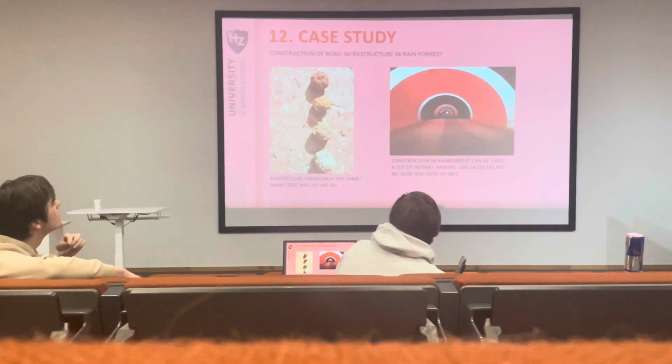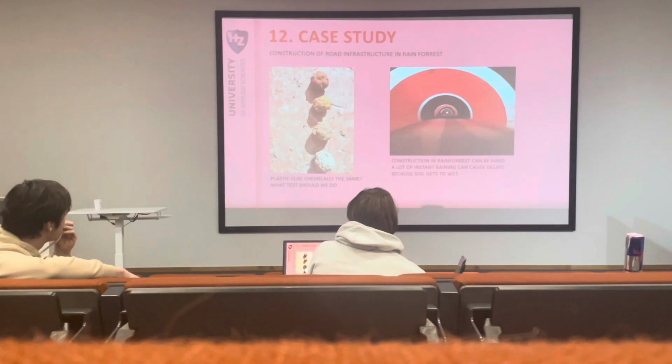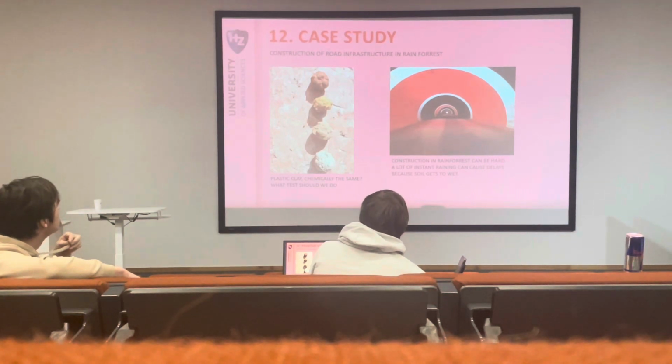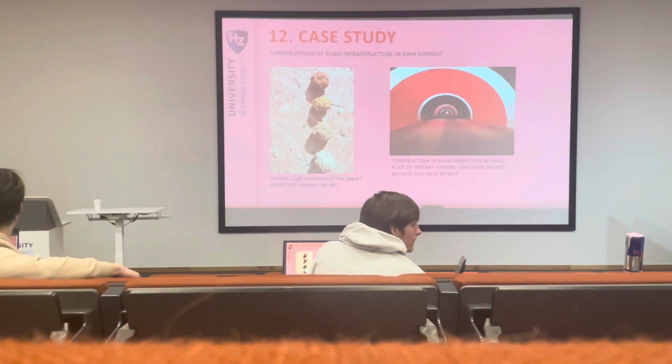There you can see also the different types of chemistry of clay that you have in the Amazon region. You see iron, limestone, etc. You have a bunch of mixture, and why that is important, because when you do a cement stabilization, you need to be aware that you can get different results every square centimeter.